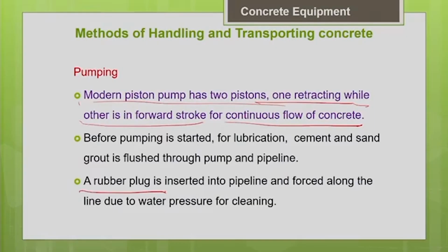After the concrete pumping is done, you have to clean the pump and the pipelines immediately. Otherwise, if the concrete hardens, it's very difficult to clean. Very commonly, they insert a rubber plug into the pipeline and flush it along the pipeline with water pressure. This rubber plug will clean away everything perfectly, so that there won't be any choking of aggregate or anything in the concrete pipelines. This is the device they use to ensure that there is no choking or blocking in the pipeline.